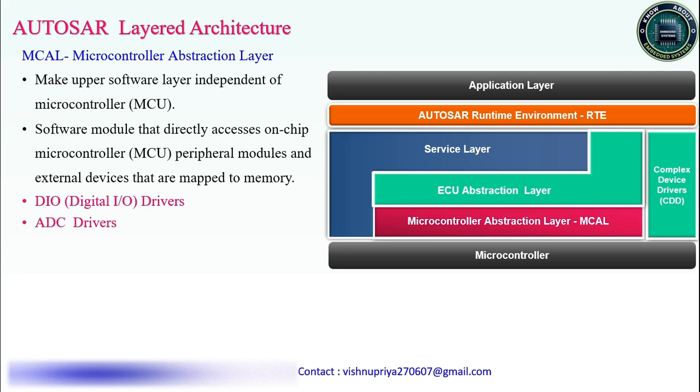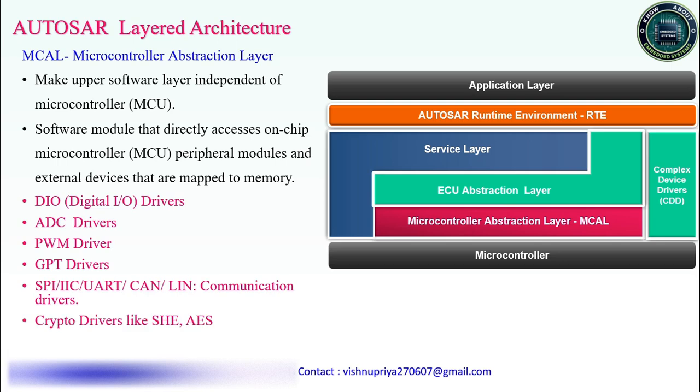Third important thing: what are the different drivers we're going to develop in MCAL? We're going to develop digital input output drivers, DIO, then ADC drivers, PWM drivers, and GPT, which stands for general purpose timers. Then we have serial communication drivers, namely SPI, I2C, UART, LIN and CAN.